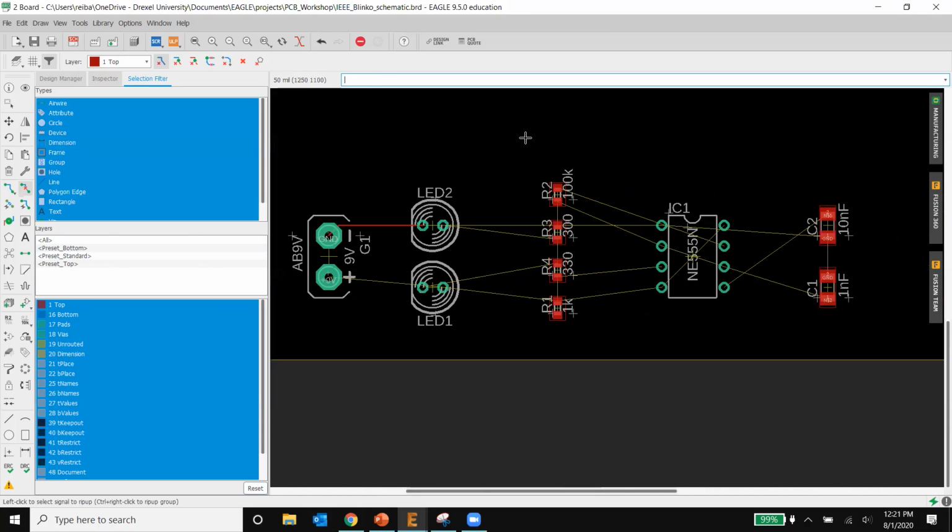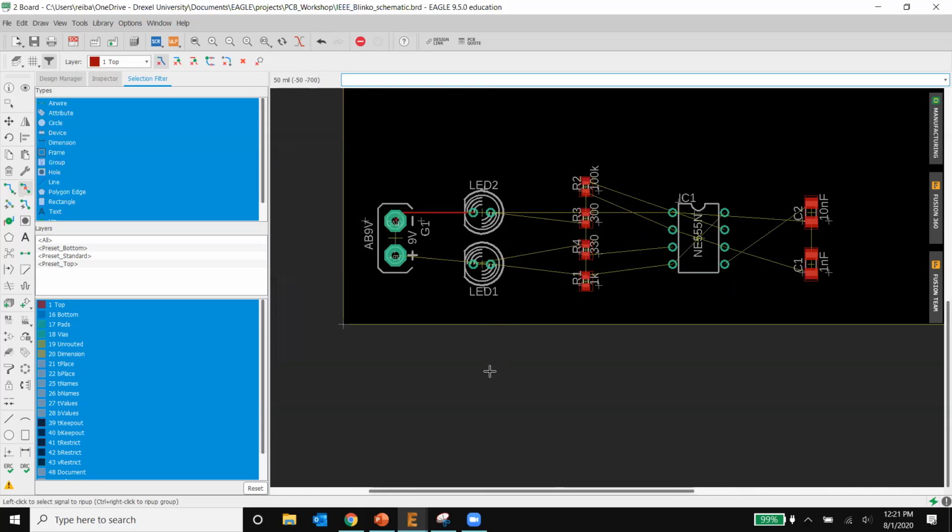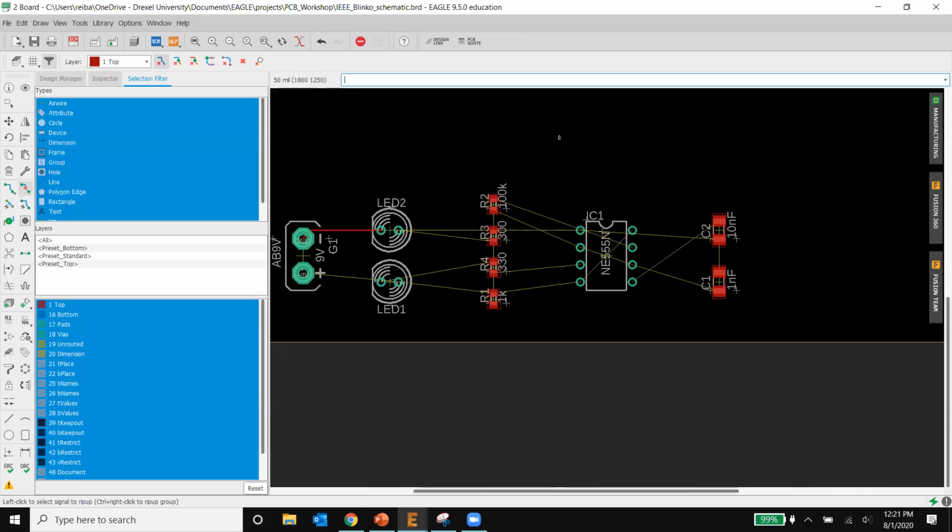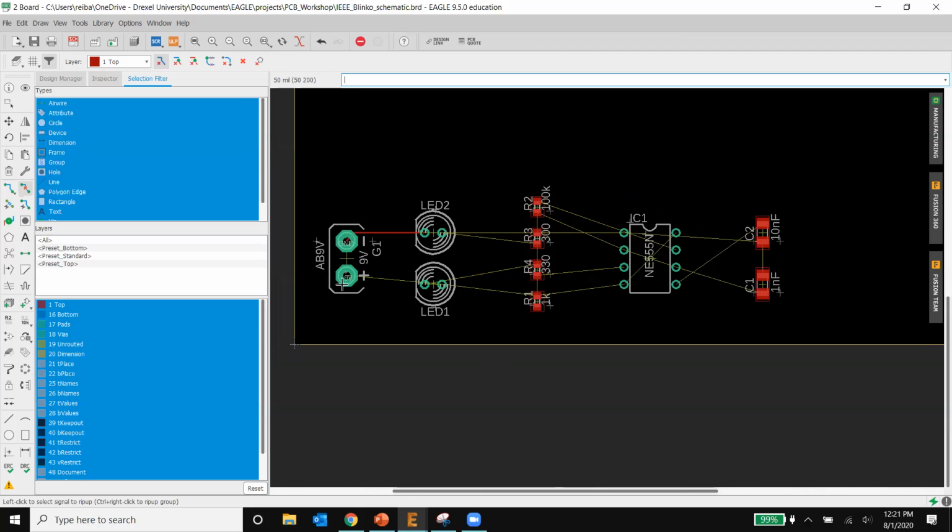So what I want to do right now is show you guys, before doing any other traces, how to do the grounding here, because you don't see any power supply going through or anything. The power supply is going from here, right? As I said, that plus 9 volt is making the wires here, and this negative is going here. But this has to be grounded. No, I'm sorry, this is the minus. This has to be grounded. But where is that ground going? Because it needs to be grounded, basically.